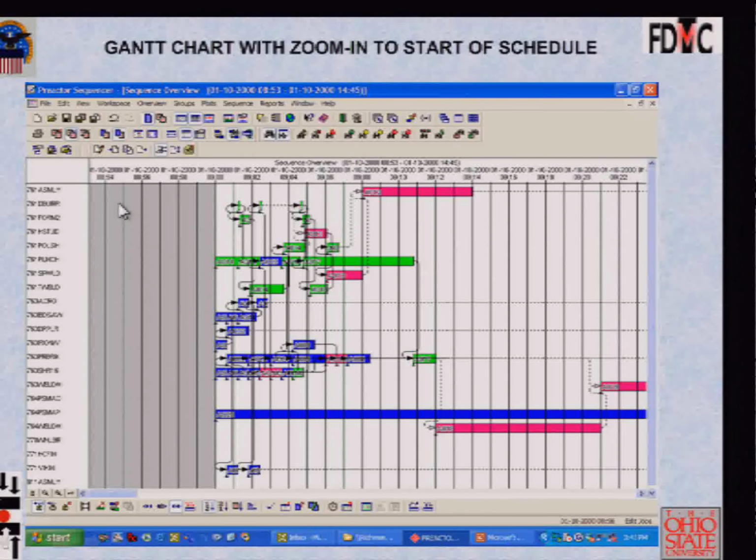So with the combination of group technology, production flow analysis done using FAST, layout design, and finite capacity scheduling of the total facility, making this product or a family of products, you have essentially the coming together of the value network mapping methodology. And the last element of the value network map, based on what value stream maps provide, is the value added ratio. That's number 7.